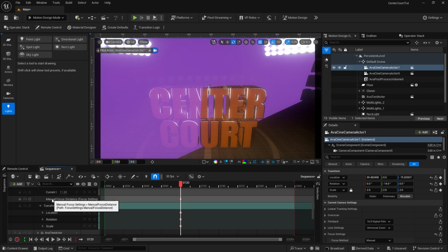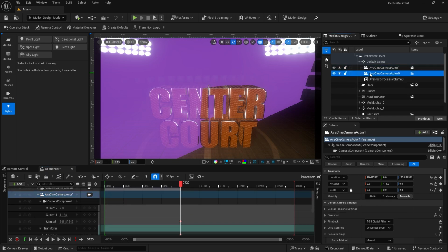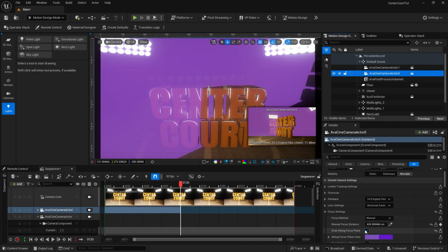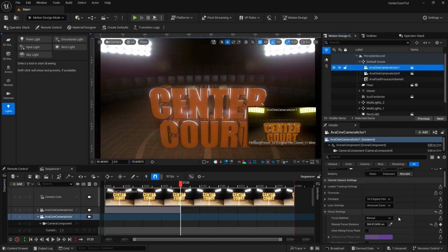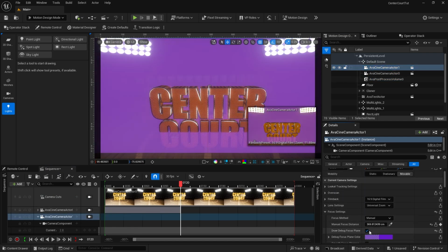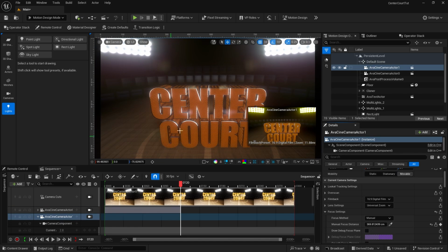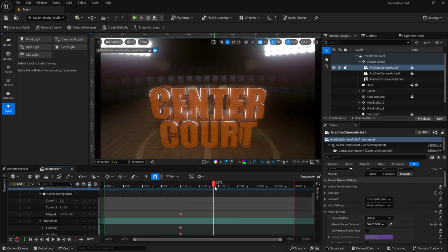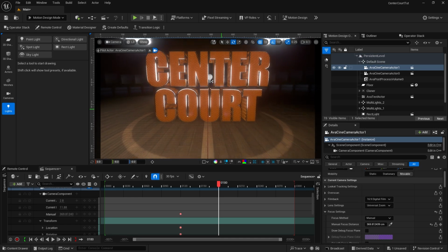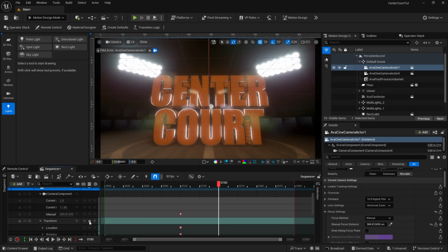And then on the focus distance right there, let me check it for that camera. I'll actually need to deactivate it in the first camera right there and go to my second camera and activate it there to make sure, okay, that looks good. Deactivate it real quick. I'll jump ahead and go to about 180, and I'll bring that camera down, rotate it a little bit, and set a keyframe on those properties. So we have our second animation.